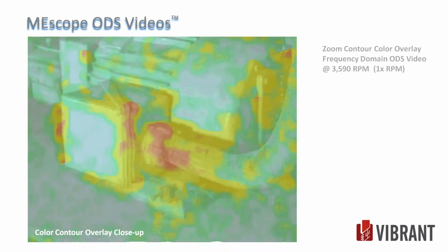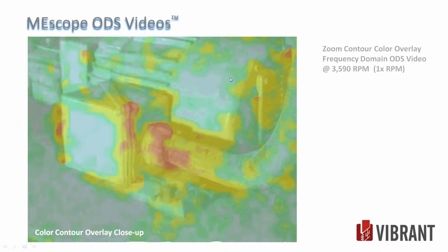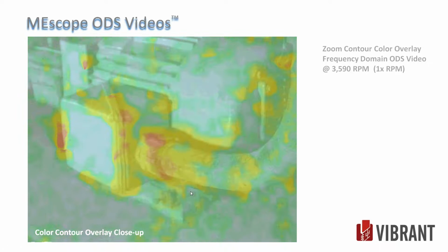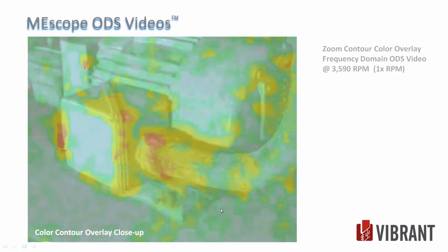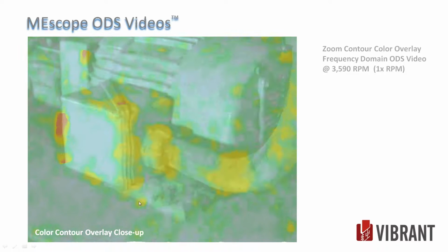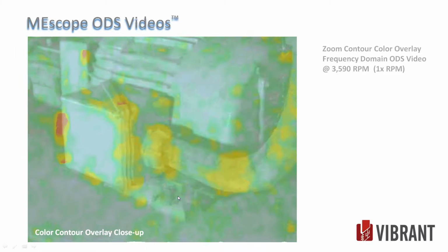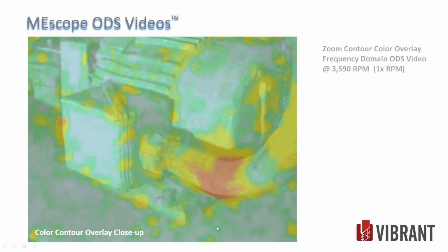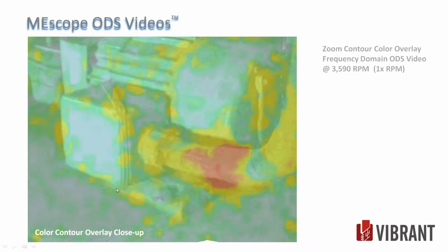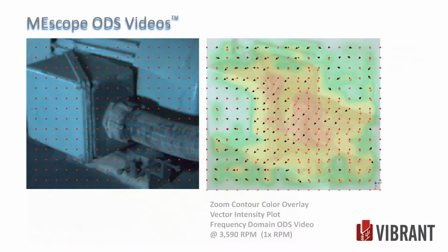We did not zoom. This is not a zoom or cropped image. This is another image that we took. So it has all the pixel value in here. Still have all the motion in the electrical box, but down here where it should be all grayed out as no motion, this corner where the motor foot's bolted down also has motion where it shouldn't be. It should look more like this, where it's all grayed over here. I'll show you a little better image of that.